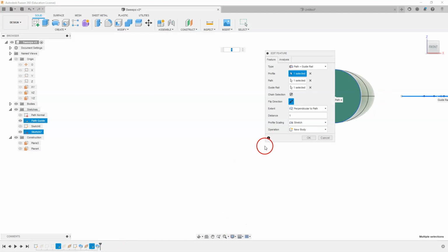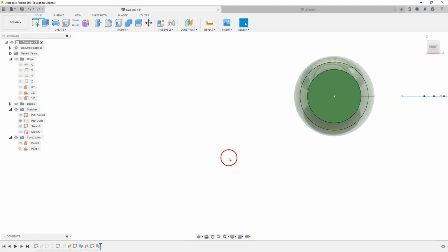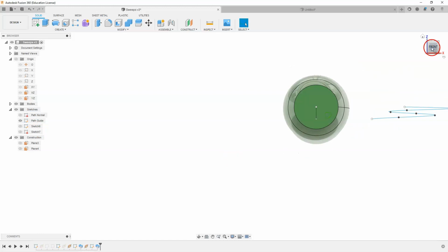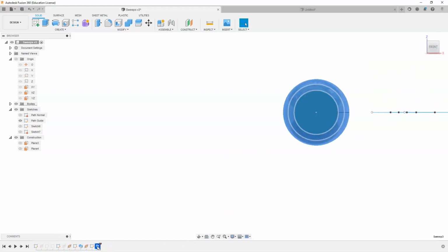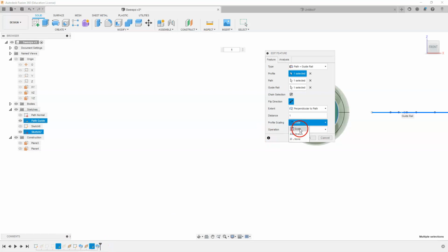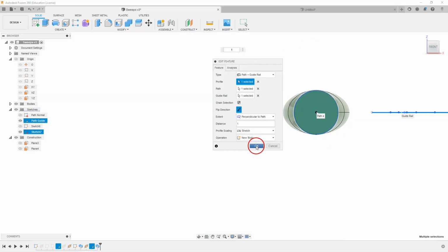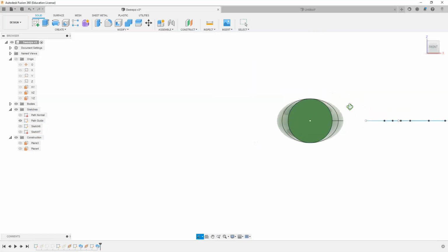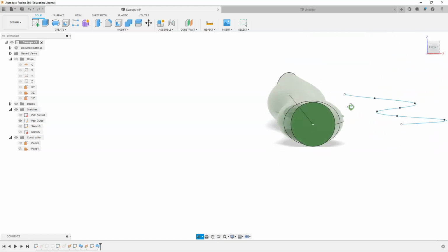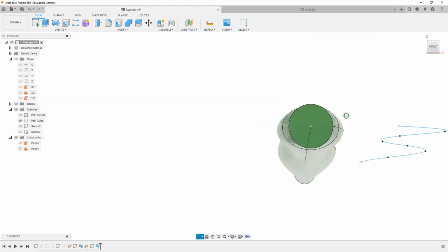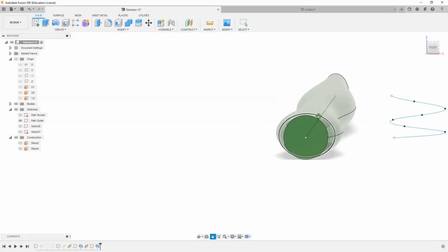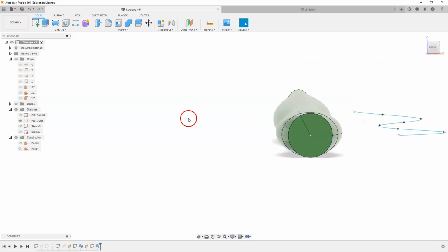So if I went back to this option and changed this to scale and a value of 1 there, you'll see it is round all the way around, perfectly round. Back again to my scale and select stretch and select OK. Pull this aside, select OK. And actually you couldn't see too much change there, but the horizontal distance has changed, but has maintained the vertical distance.